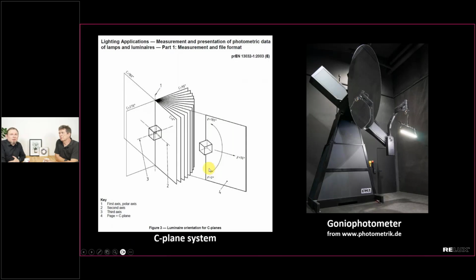And this is organized in the Eulumdat file. So the C-plane system is what we are typically using in technical lighting, and that's what we are normally doing in lighting calculation. There also exist an A and a B system. I guess the B system is sometimes used for car front lights, and not floodlights. And the C-plane is similar to when you cut a cake from the top down. That is what we call a C-plane.